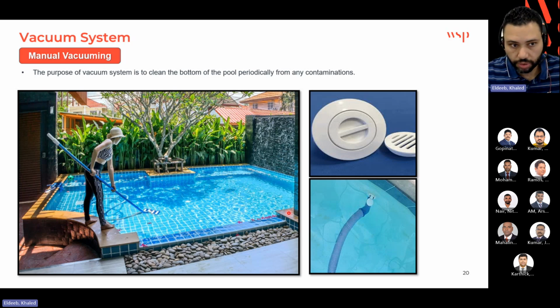So two sides should be connected to the board and this head, okay. Then we need to prime the hose because it is not full with water, it has too much air. We will submerge the hose to fill it with water and remove all air bubbles to maintain the suction. Then start vacuuming.